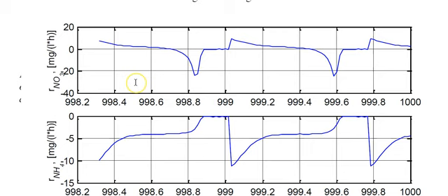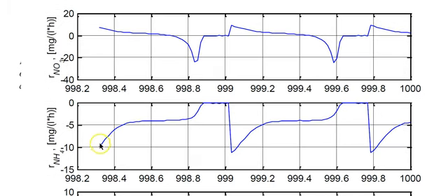Now here come some graphs just illustrating what's going on. The rates, like rate of nitrate production. So here the air is on, so we're producing nitrate, then air is off, and we're consuming it during denitrification. So you can study that a little closer, and we see that when nitrate is produced, ammonia is removed.